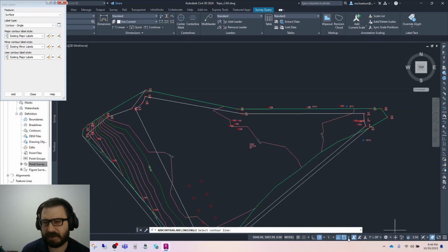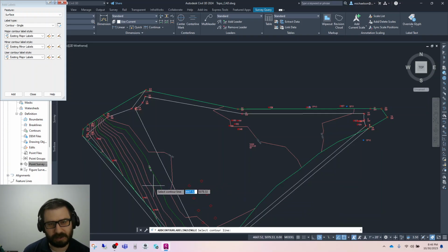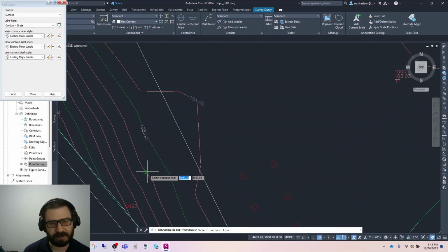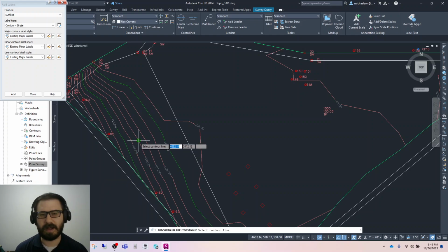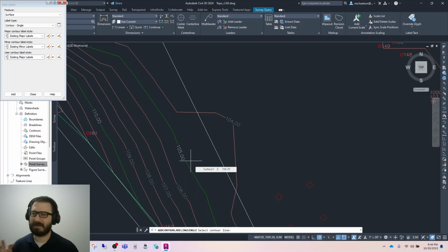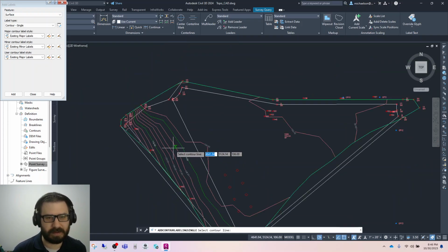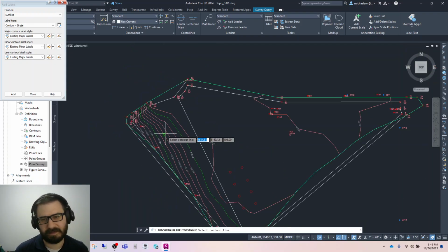105. If you want, if you go into the object snap at the bottom, you can add the term nearest. If you add nearest, it will actually pick along the line a little better. So if you want a little more flexibility on where it goes, maybe we'll put it right there, or right there, or right there. It'll give you a little bit more resolution. And again, notice how on the lines at every 5 feet, the lines are a little bit brighter and the labels are a little bit different. That's just making sure it's clear for you as the user.